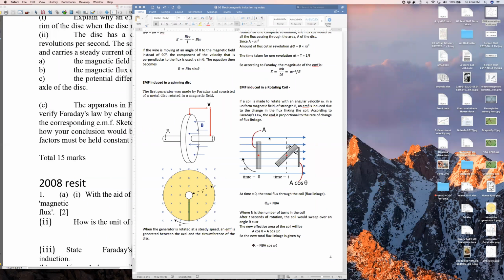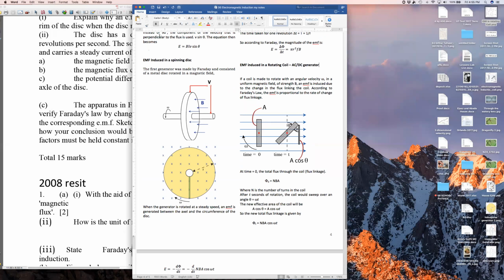Believe me or not, in both the AC generator and DC generator, AC is produced inside the coil. I will clarify this in class when I get the appropriate video, but an AC is always produced inside the coil, whether it's an AC generator or DC generator. So I'll put AC slash DC generator, both of them. How you get a DC out of the DC generator is you use a commutator to rectify it. Again, I will show you that. I'm not going to invest the time on that right now. Our time is being spent dealing with Faraday's law.